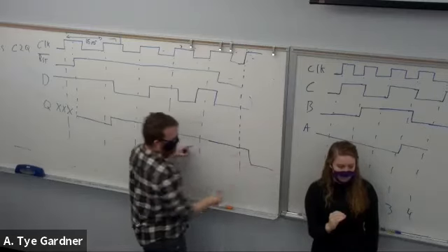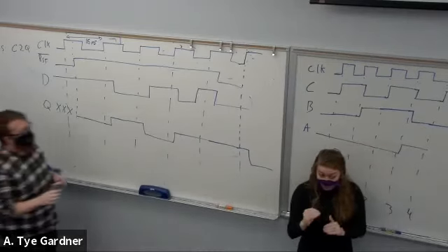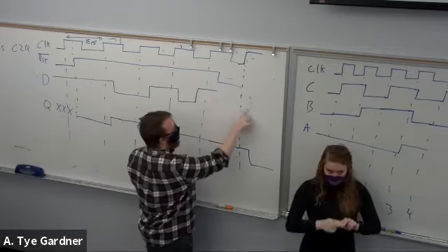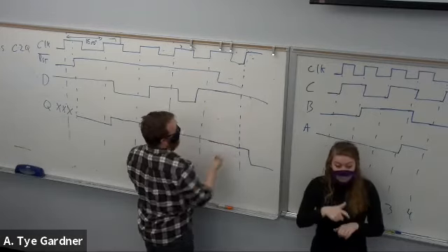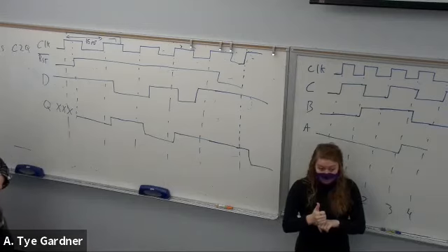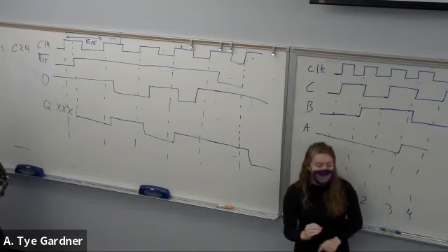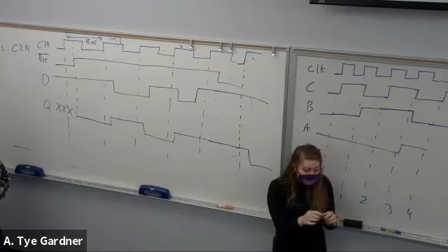And a reset, you already said, goes to 0. Okay. So if D is 1, but then reset is 0, you would reset at the next clock point, if it was 1, but you would be resetting, would you still drop to reset even if the data is high? Yeah, the reset is the most important thing. Okay. And reset, unless you say otherwise, reset always means go to 0.